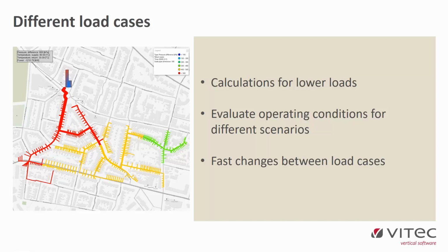We can adapt to changes according to outdoor temperature. So we can set, for example, fixed supply temperatures that are dependent on the outdoor temperature. Both the return temperature and the heat load of each consumer can be connected to the outdoor temperature. You can either group them to easily change all at once, or you can change them individually if they react differently to changing temperatures.